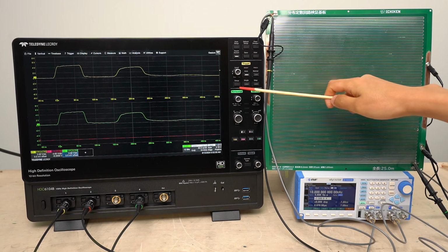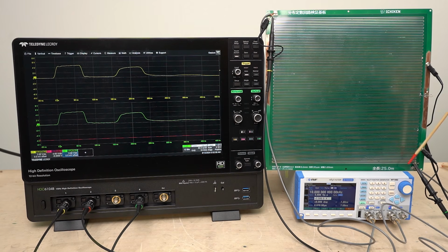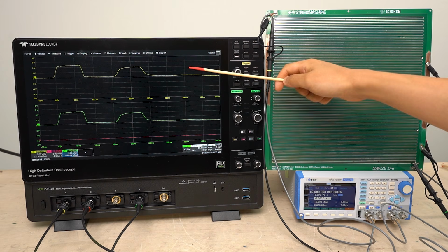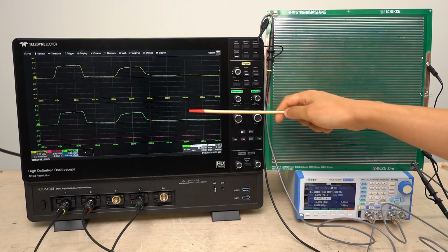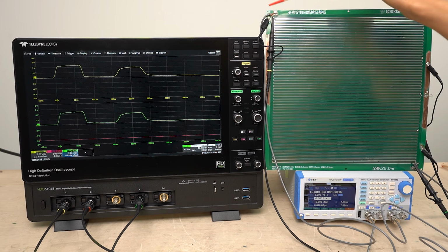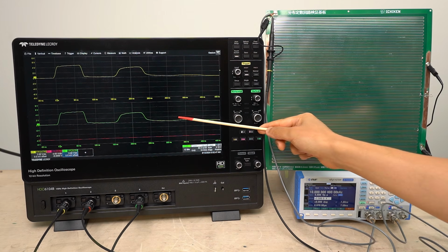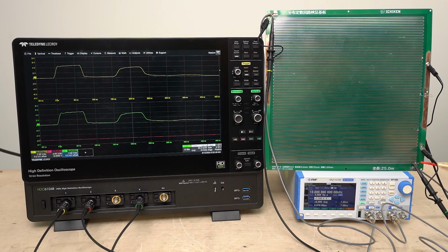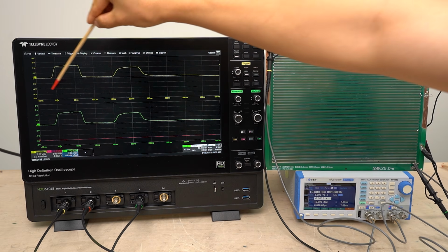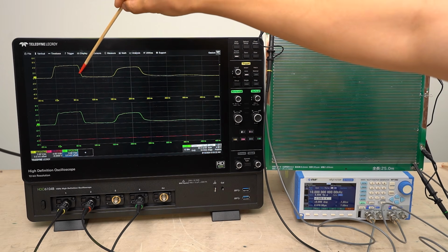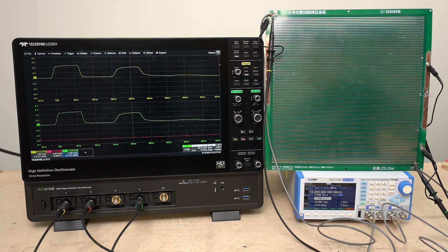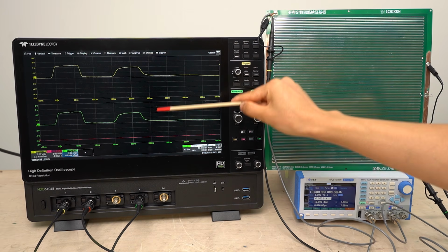Let's try a different experiment. I'm sending the same waveform signal from both the input terminal and the end terminal, and then something interesting happens. The waveforms are a bit tricky to read, but I'll use them to explain. The yellow waveform shows the voltage at the input terminal, and the green one shows the voltage at the end terminal. Here we can see the first peaks. This is the pulse voltage applied to the input terminal, and this one is the pulse voltage applied to the end terminal. After that, we can see another pair of peaks.